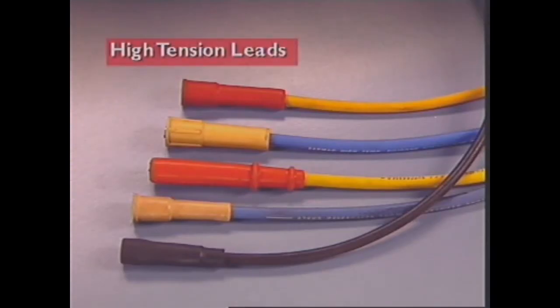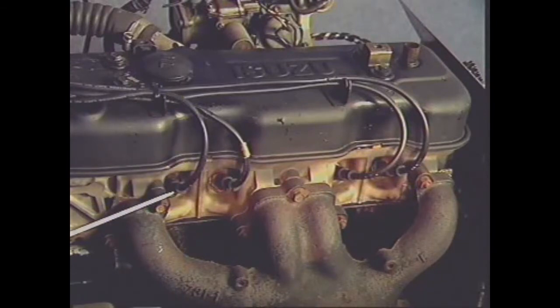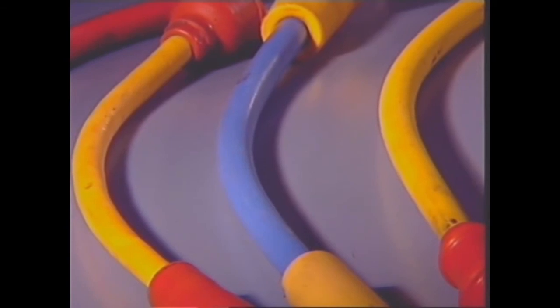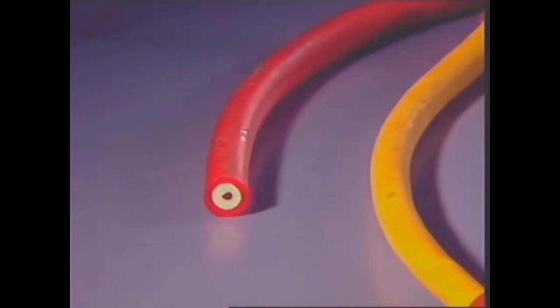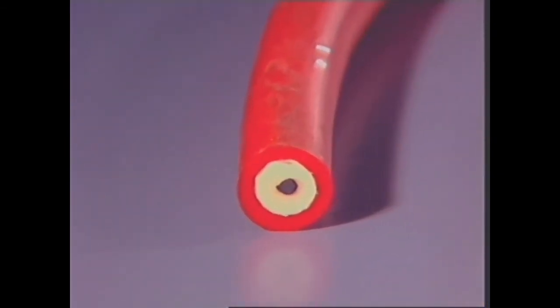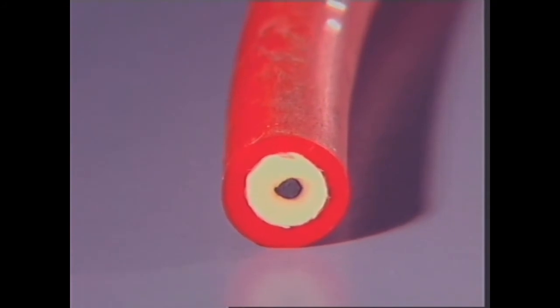The high-tension cables conduct the high output voltage generated in the secondary ignition circuit when each ignition pulse occurs. They link the high-tension terminal of the ignition coil, the distributor cap, and spark plugs. Because of the high voltage, the cables are large in diameter and are made from thick-walled insulating material around a central conducting core. The heavy insulation prevents leakage occurring and also withstands the effects of high temperature, oil and moisture.